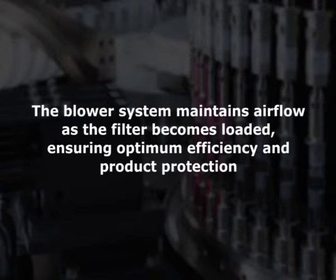The blower system maintains the airflow as the filter becomes loaded, ensuring optimum efficiency and product protection. An additional disposable pre-filter traps the large particles in the inflow air prior to reaching the main filter. This protects it against damage and prolongs the filter life.